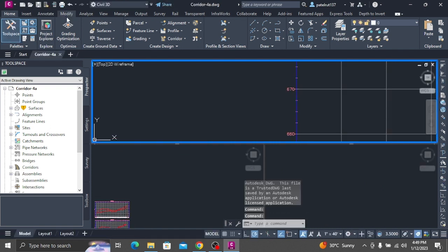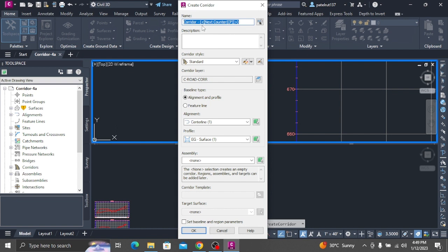Click Modify tab > Design panel > Corridor. Click Corridor tab > Modify Corridor Sections panel > Section Editor. On the Section Editor tab, on the Station Selection panel, in the Select a Station list, select 0+00.00. A cross-section of the corridor at the starting station is displayed.